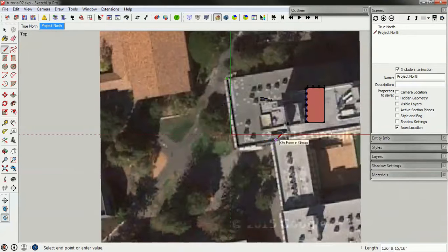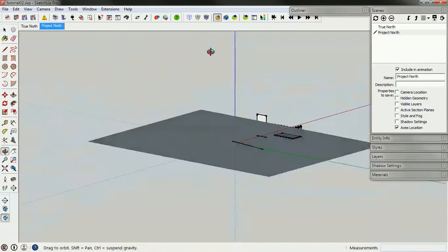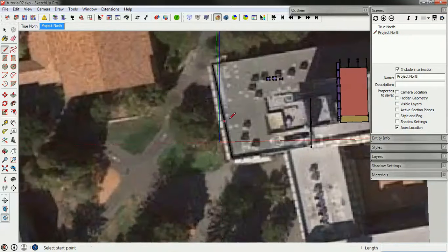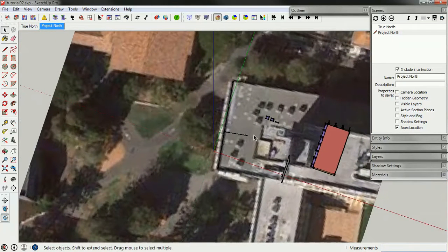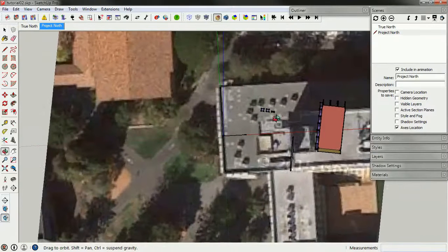that face. And I want to also do what's perpendicular to it, which I can do by starting anywhere sort of in the middle, and then, oh, you know what, why is it not snapping here? I'm going to press L for line, and then there we go. It should show that magenta or pink color, and that will be perpendicular to the edge. So now I can make a new axis that looks like that. To do that, click on the axes, and starting in the middle, go over to the right and then to the top, and now I've got a new axis.